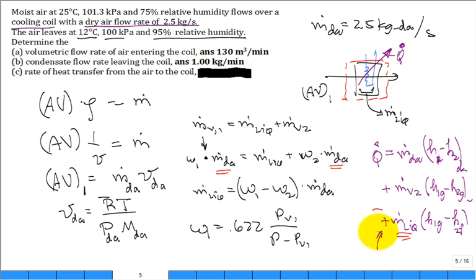And we did some calculations, and often if you have a large M dot of the liquid, that piece of the three pieces is large. Takes a lot of cooling to condense water vapor. So you compute 75.5 kilowatts. Ready to move forward?